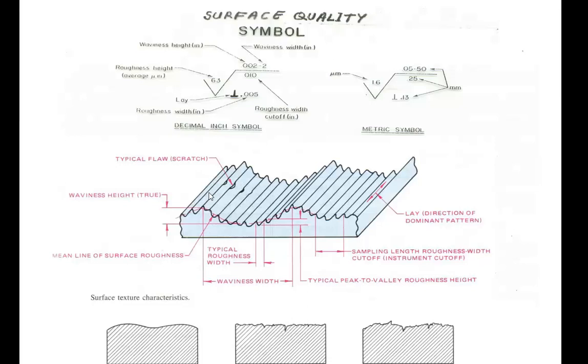Mainly these are set by the edge of the cutting tool during the cutting process, or by the abrasive particles of the grinding wheel during the grinding process, as I said, or if the object is a cast, during the solidification, sand particles of the template will create a certain pattern over the surface of the object.